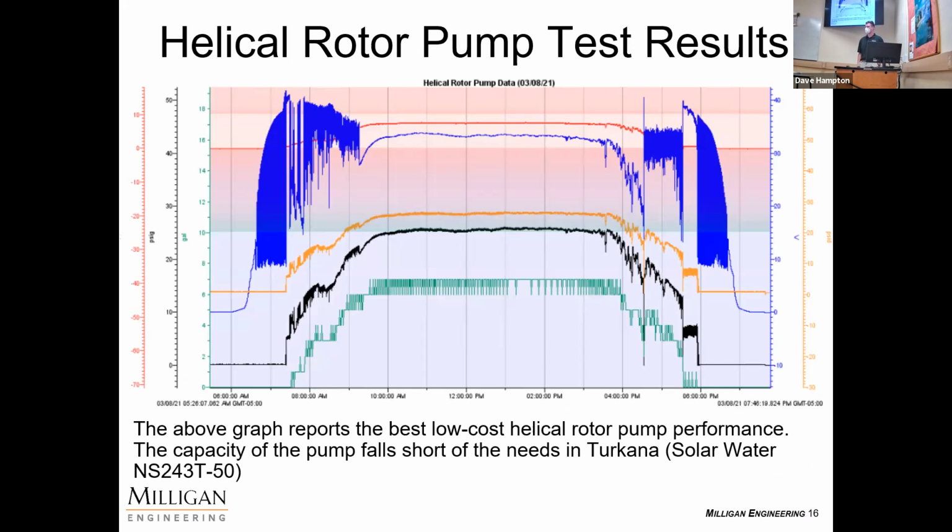Question about the voltage and reliability of the Grundfos. Did you do any testing or analysis to come to that conclusion that increasing the voltage would improve reliability? We got that straight from the Grundfos engineers. We were able to contact them. That was their recommendation. They told us that, while this is not official Grundfos literature, they have experienced pumps being powered with low voltage and failing prematurely.